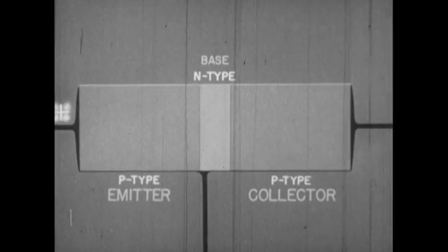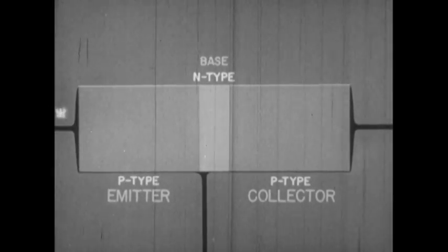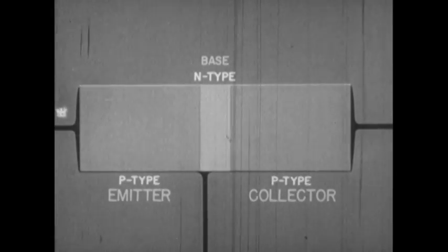When an AC input is applied to the emitter, the number of holes injected into the base varies with the changing emitter voltage. Surges of holes travel through the base to become positive peaks of the collector current.